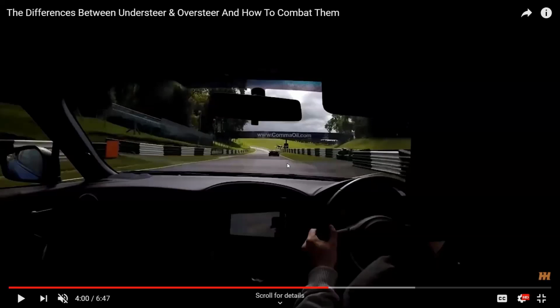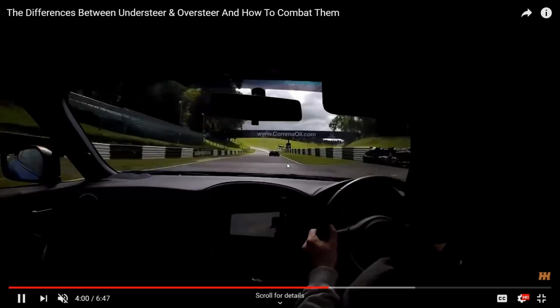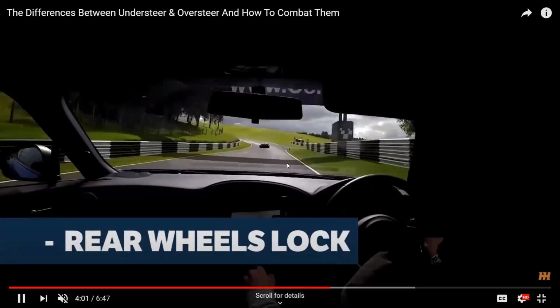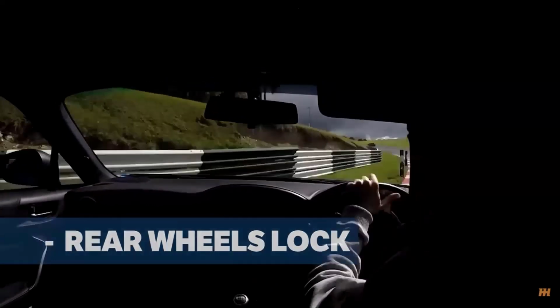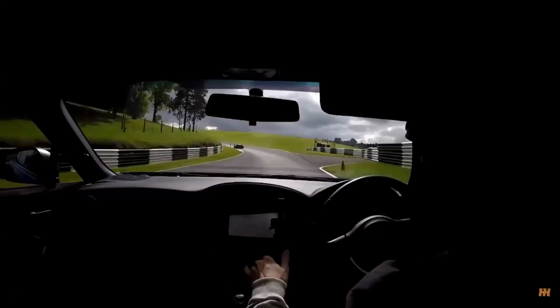So if the driver is making a turn at that time, obviously the rear wheel will be skidding, and as he is making a turn, there will be a rolling. That is what is happening here. He is putting the vehicle in a low gear and making a turn, so he is hitting the obstacle. The rear wheel is locking.